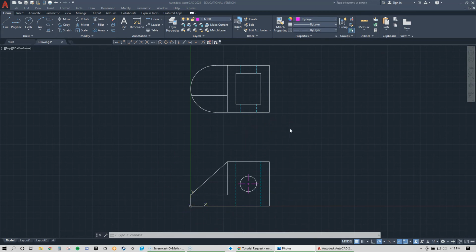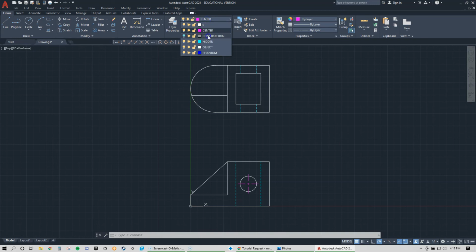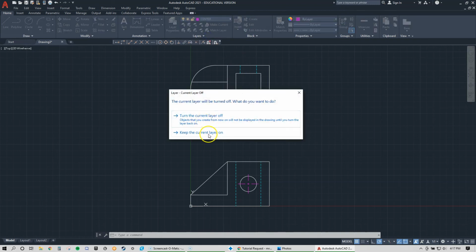But I'm going to tell you that if you were going to make a drawing, your primary view cannot be a section. That's a standard drawing rule. I know people do it. It's wrong. I'm just telling you flat out. So what we'll do is we're going to turn our construction back on.